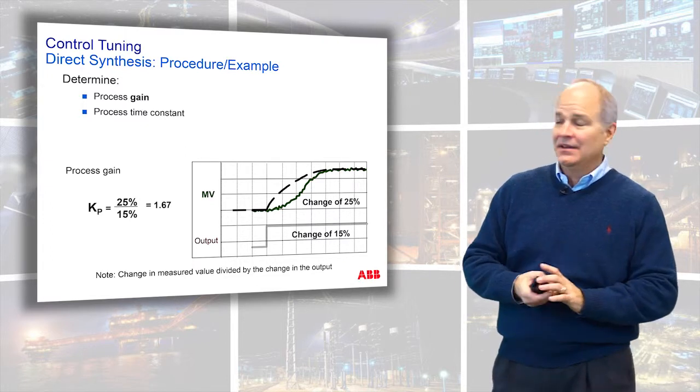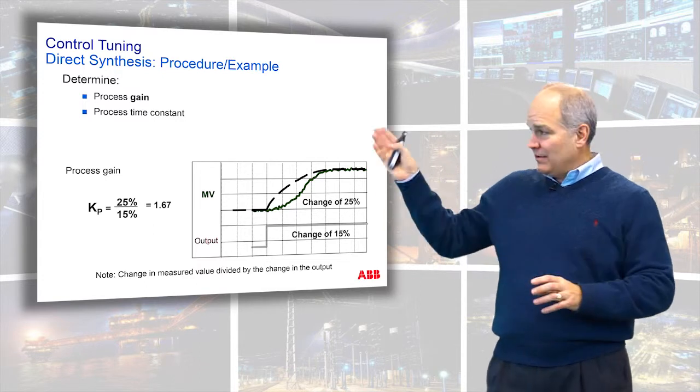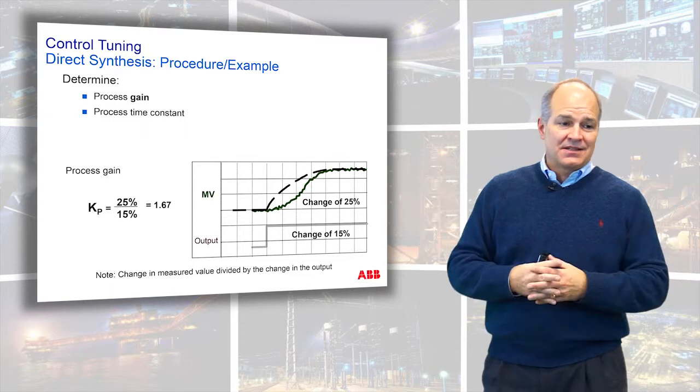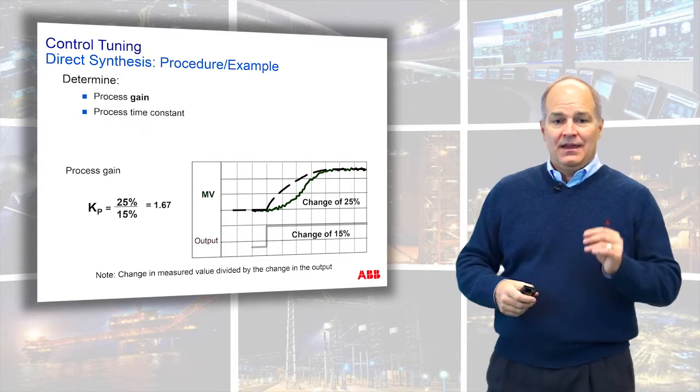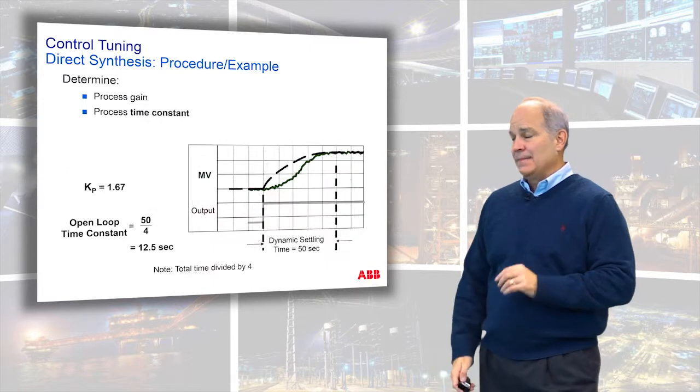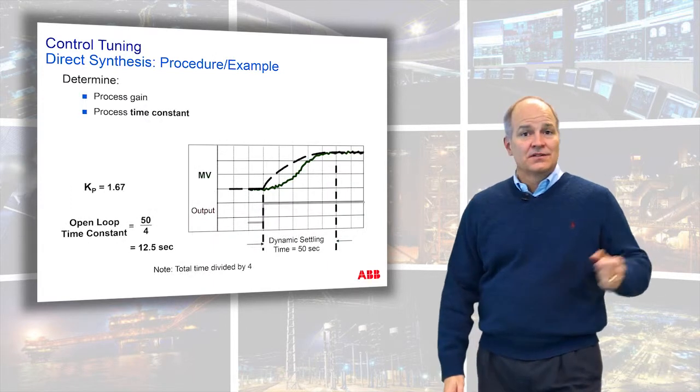Is pretty accurate. Between there, your process gain is, well, constant. On the ends, your process gain can be really, really different. And that's why I like to look at my valve position when I'm getting ready to do this change, this bump test, or over history.